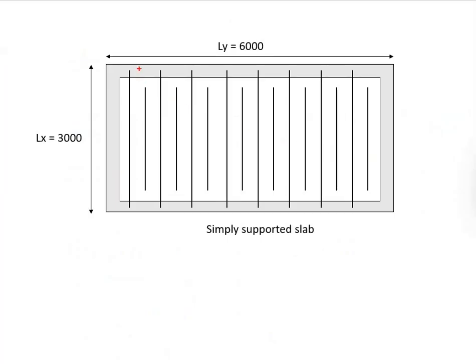And then near to the support, you do the curtailments of reinforcement bar, one for every couple of the reinforcement. Initially, the spacing is 50. Now the spacing near to the support is 100. Double the spacing. Where do you do the curtailment?